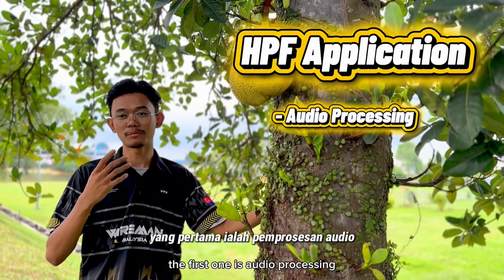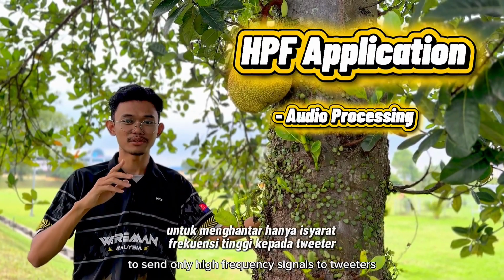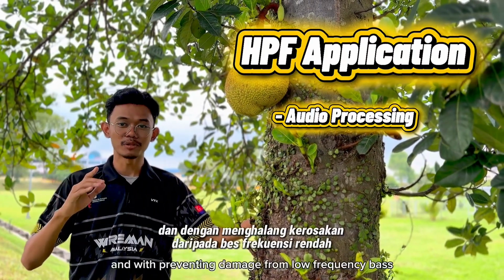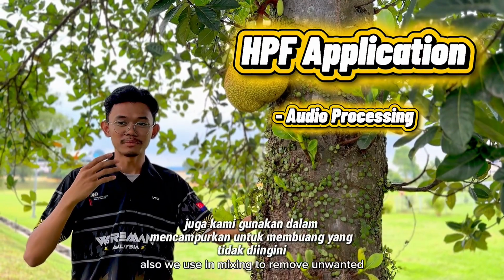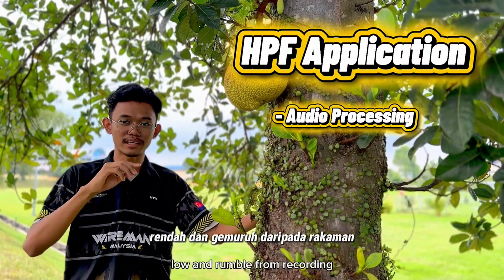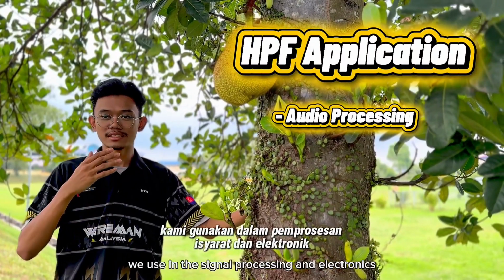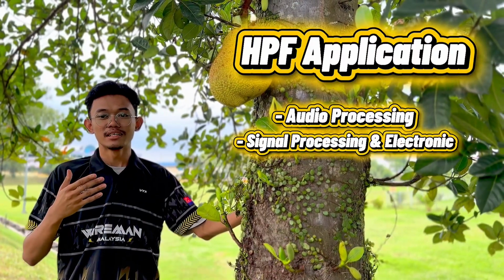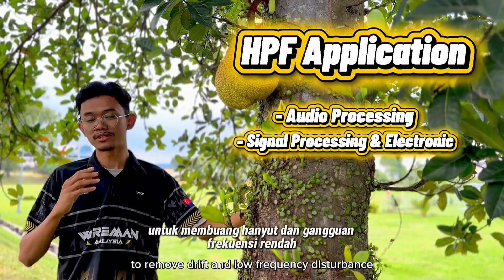The first one is audio processing. We use it in speaker systems to send only high frequency signals to tweeters, preventing damage from low frequency bass. Also, we use it in mixing to remove unwanted low rumble from recordings. And the second one, we use it in signal processing and electronics, in sensors and control systems to remove drift and low frequency disturbance.